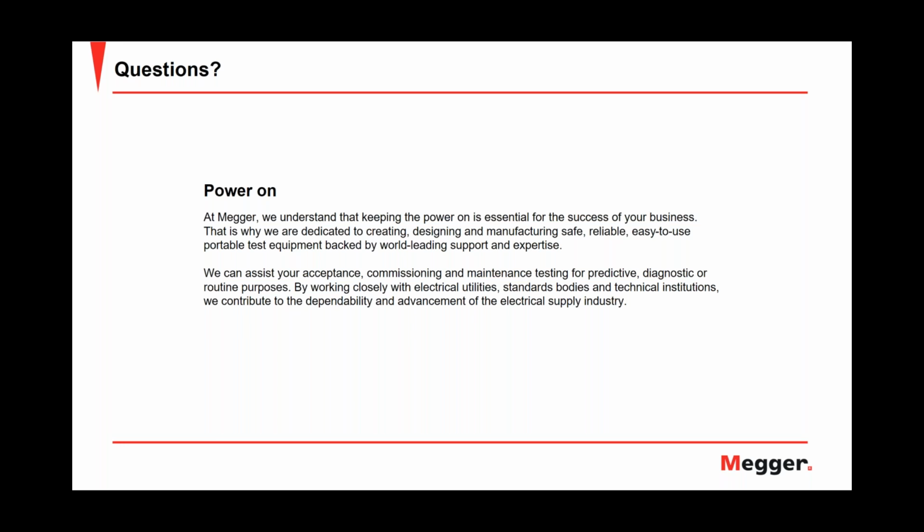If you then have a flashover that, yes, flashes over to a shield, but it's not the shield you connected, then you won't see anything. It's the same with the more advanced methods that go beyond arc reflection. All of these methods, or the methods that Javier has described in this webinar, can in principle be applied to high voltage cables, but always take it with a grain of salt. It's always more difficult. You have to consider not just the cable construction itself, but the whole installation, the way it is made, which has a big influence on how difficult it can become. But in principle, we know this from measurements on high voltage cables that we sometimes get from our customers, that things are possible.